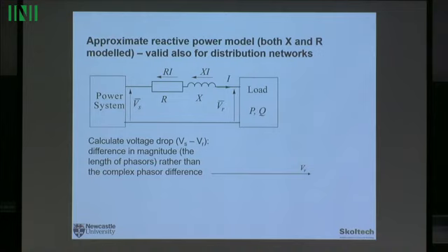So now again, let's do the phasor diagram, but including the resistance. So again, we start with Vr. Again, we assume the angle phi, but now Vs will be Vr plus Ix plus Ri. Ix is 90 degrees with respect to the current because it's reactance, but Ri will be in phase with the current. So this is the current, we'll have both components, and now we have to add the vectors, because Vr plus Ix plus Ri must be equal to Vs. So we are building this relationship.